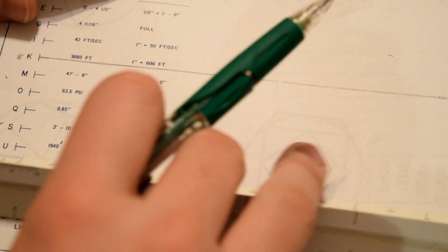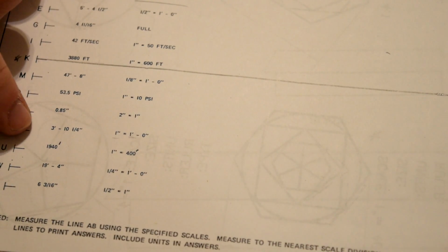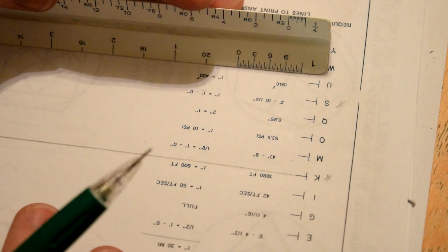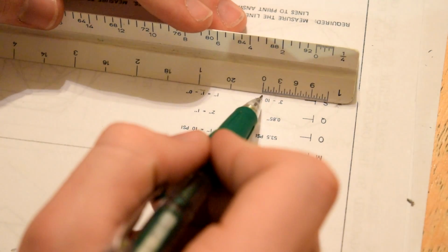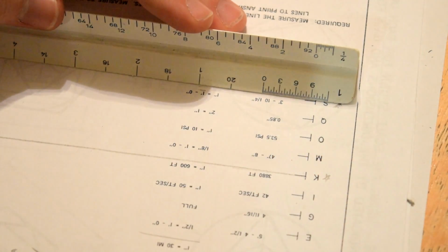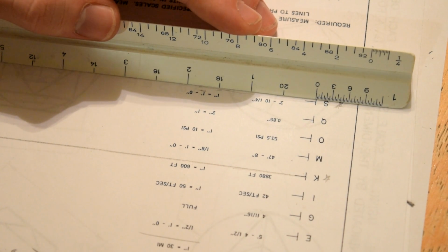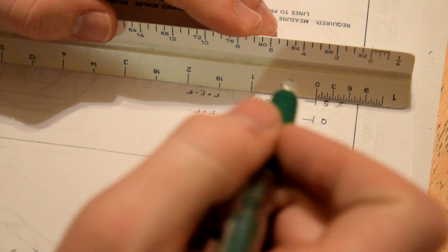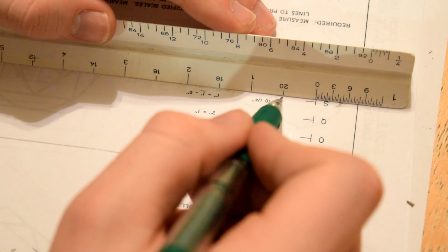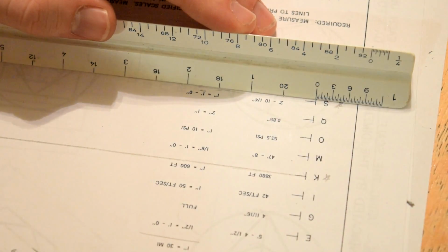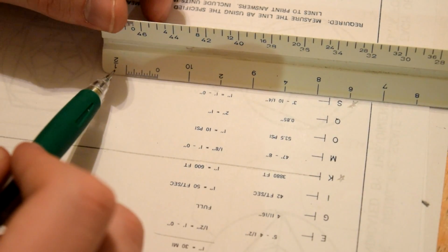Okay, I'm going to have to flip this upside down again so we can see. So I'm going for 3 feet 10 1/4 inches. My scale is 1 inch equals a foot, so I know that every inch of distance this way is 1 foot in reality, and I'm looking for almost 4 feet. Since I'm working with the big marks here, you can see there are 2 sizes of marks, the slightly taller and the slightly shorter. We can see that on the other side of the scale I've got a half.